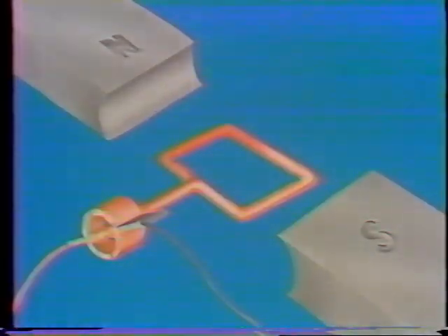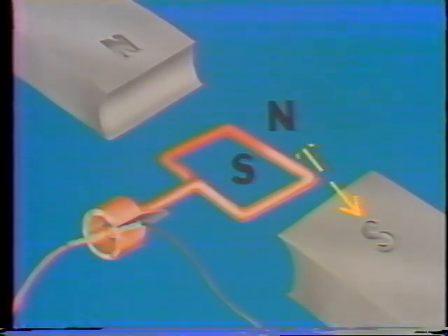You can see what I mean here. When voltage is applied to the loop, current flows through it. Now remember when we said that current flowing in a conductor produces a magnetic field? Well, that's exactly what happens in the loop of this motor. A magnetic field is produced with a north pole and a south pole perpendicular to the loop. This is our second magnetic field. The north pole of the permanent magnet attracts the south pole of the loop. And the south pole of the permanent magnet attracts the north pole of the loop. The force of this attraction is what turns the loop.